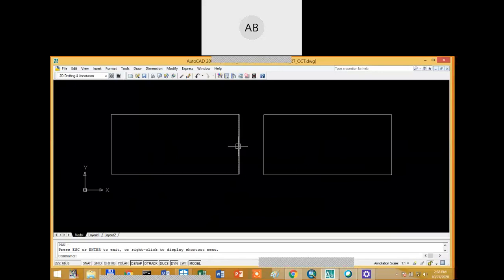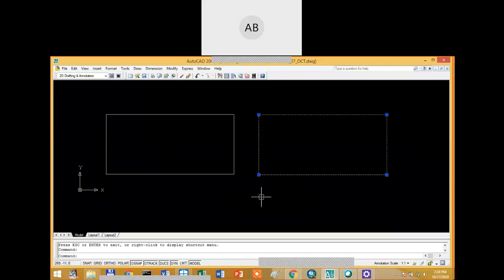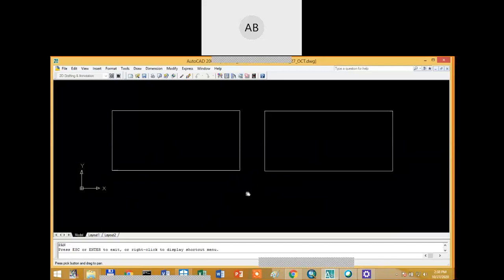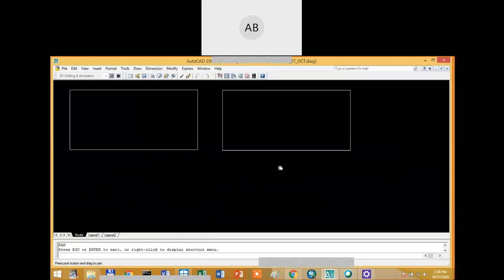You can draw it either using the line or the rectangle. But if you use the line command, it has got one entity each. If you use the rectangle command, the whole brick is one entity. You can also make a block of these two things. But before I make a block, I will switch off the UCS using the UCS icon and turn it off. I am not comfortable when the UCS is turned on. Okay, so this is the plan view, my elevation.